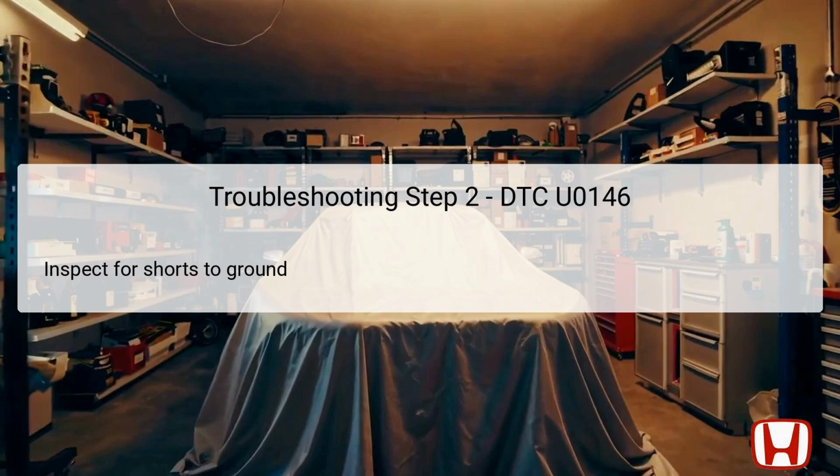A short to ground means that an unintended electrical connection has created a direct pathway from the circuit to the ground, which can lead to erroneous signals being sent to the TCM. Technicians must methodically check the F-CAN AH and AL lines for any signs of exposure or damage that could cause such a short.